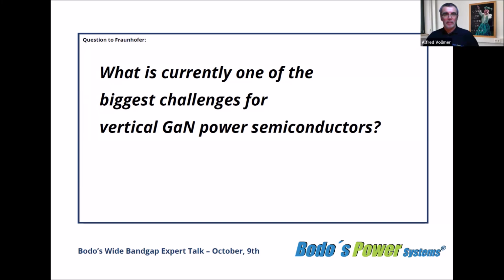What is currently one of the biggest challenges for vertical GaN power semiconductors? Yes, thank you for the question. I think one of the biggest challenges for the vertical GaN power transistors is the economic viability, due to the very high wafer costs of gallium nitride wafers.